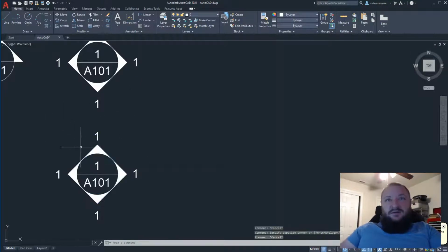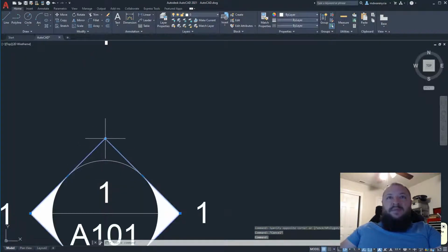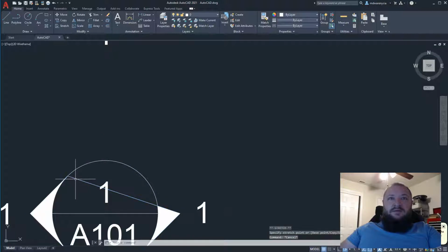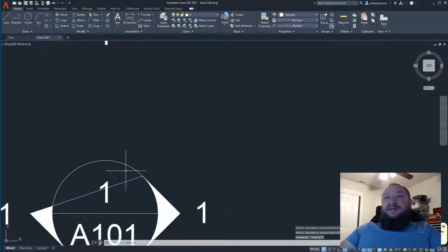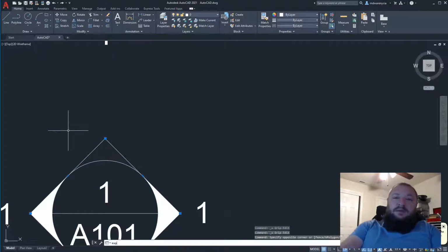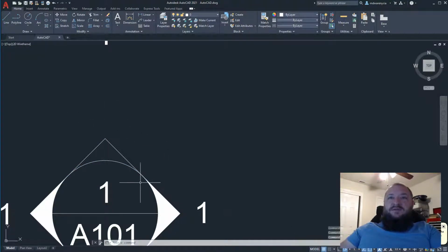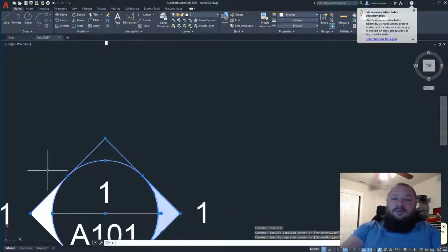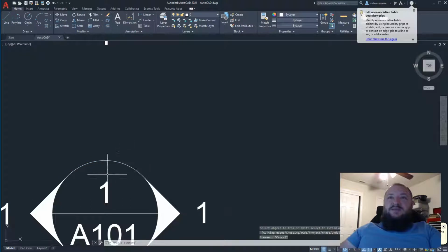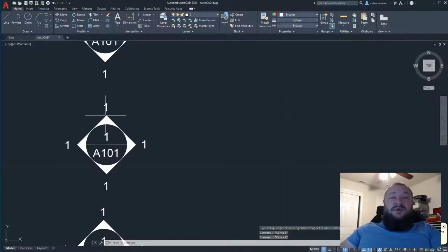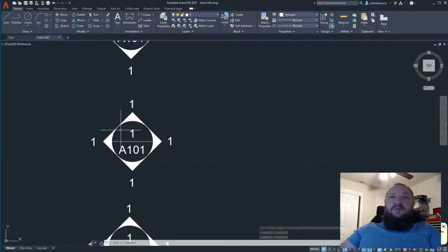So there might be, let's see here. Let's delete that and that. And then this would move to here. Oh, I've got to explode that first. Let's undo those steps. There we go. Oh, actually, let's do a trim. That's what I was trying to think of. Trim and zap that. Okay, there we go. So you'll have situations where you won't have to do the north elevation in whatever room that is. You'll have other situations where you won't have to do the east elevation in a particular room,